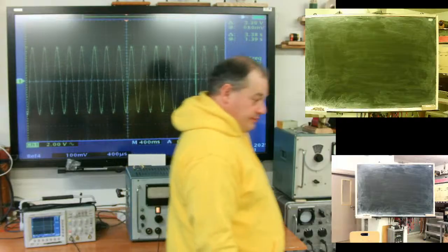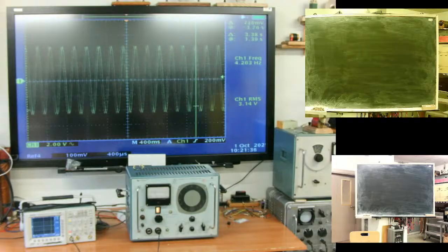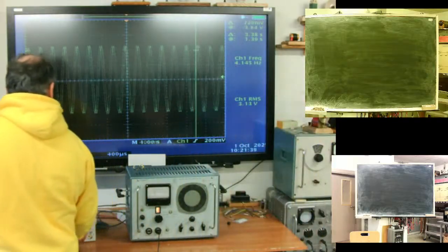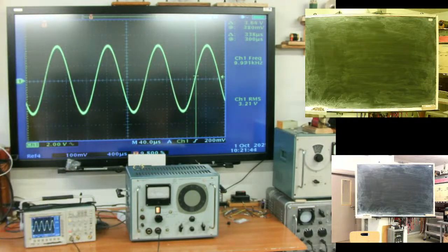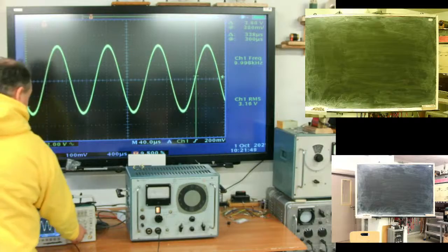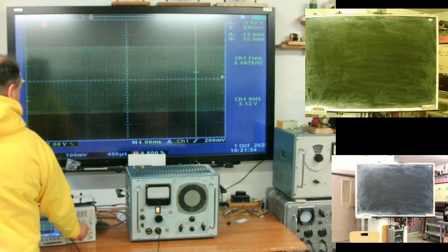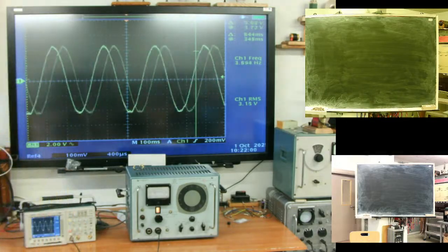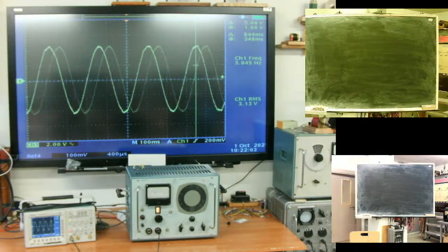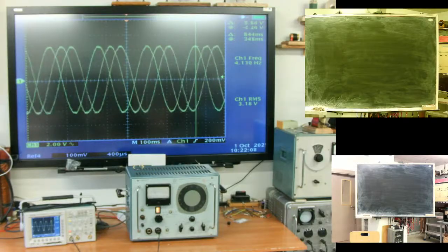Actually, did I change anything in the input signal? No. Here it is, 10 kilohertz, ideal harmonic signal. I can add another scope. I'm only playing with sampling rate. And you see what's going on? Scope thinks that it's a 4 hertz signal.